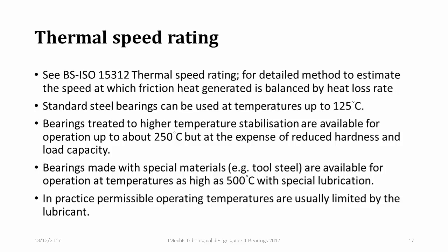In practice, this can be taken up to about 250 degrees C with regular bearing steels, but the hardness will be reduced, and so the load capacity has to be scaled back. There are some special steels available, including, for example, tool steel, which can operate as high as 500 degrees C, but that needs special lubrication, and in practice, permissible operating temperatures are nearly always limited by the lubricant.